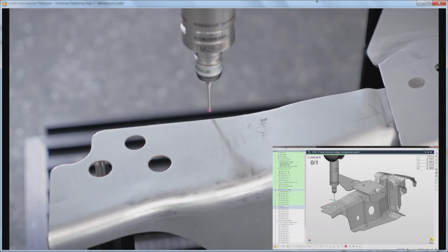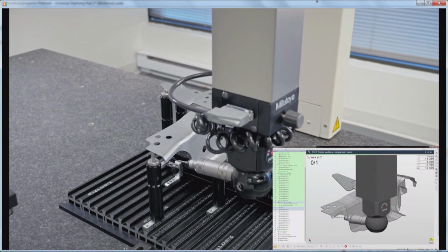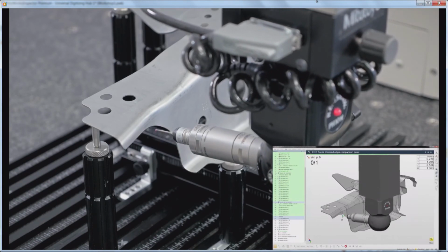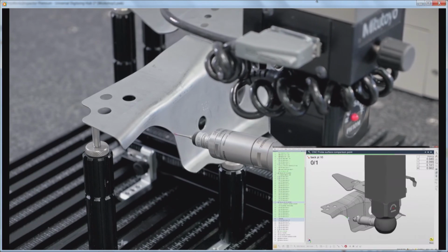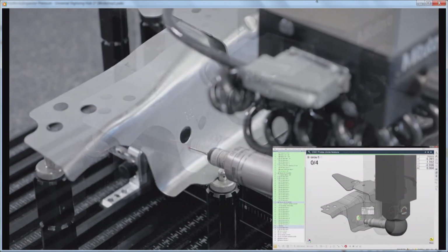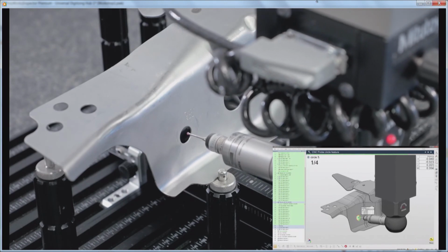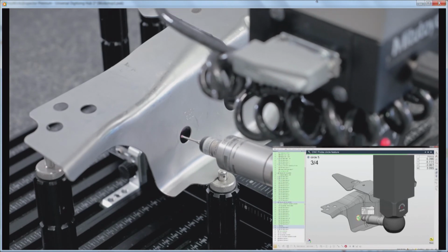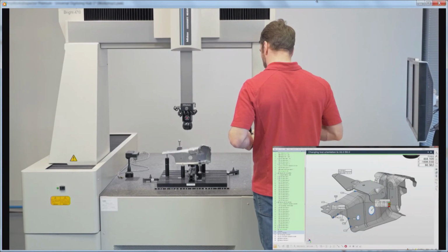Once this is over, this is where the CMM goes to a safe location, performs the tool orientation change, and we proceed with the remaining trimmed edge comparison points that we need to measure. Once this boundary is completely inspected, we will then finish by measuring our two circles. Now, the sequence is almost complete, as you can see here, and as the CMM moves up to a safe location, this is where we reach the step where we added our custom measurement objects.